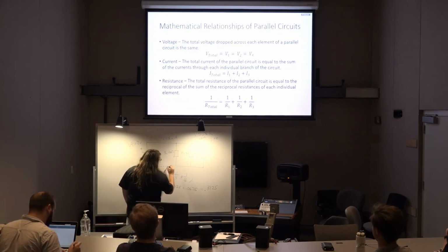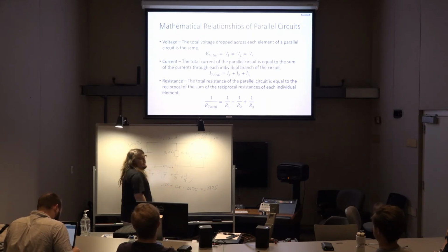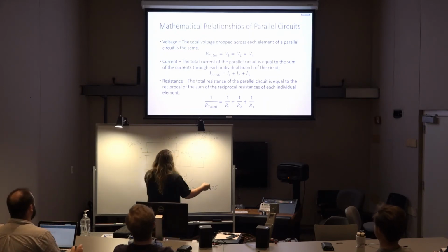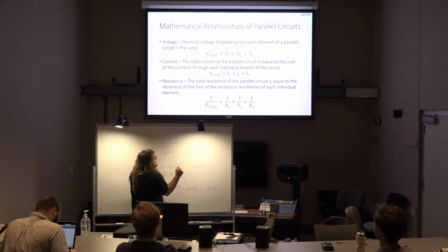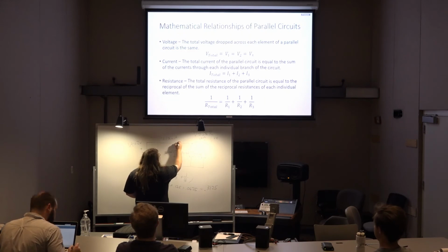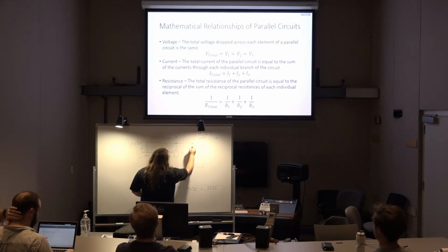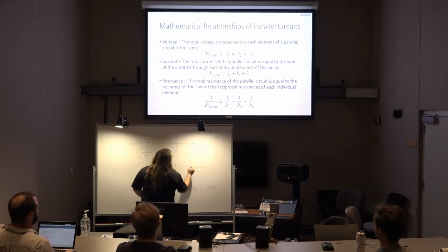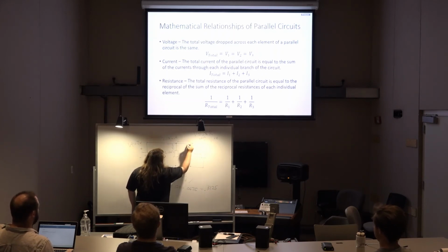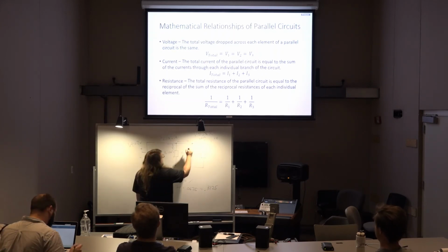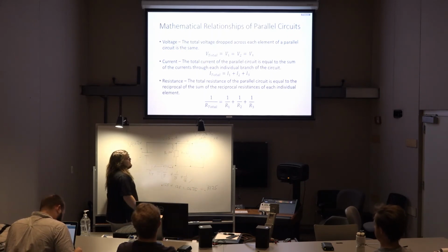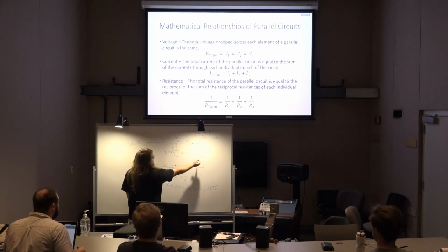And just now I'm drawing the current flow completely opposite to the way that I just did last time. See? We're all good. It's just polarity. Okay, so at this juncture here, this node and this node, current is going to split here and here, and then here and here. And the way that it splits is based on the resistances.